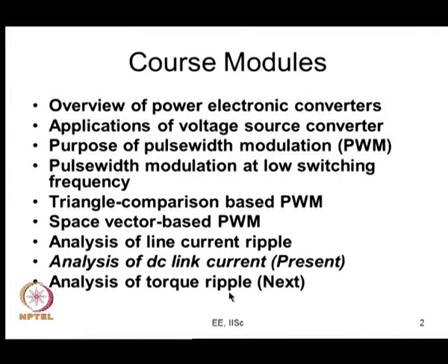That is, when you apply these kinds of outputs of an inverter to an induction motor drive, the fundamental component of the output voltage produces fundamental current and fundamental flux, and that produces a steady torque, whereas all the harmonic voltages end in generation of certain ripple. So, this is what we will do in the next module, which would be in the next couple of lectures.